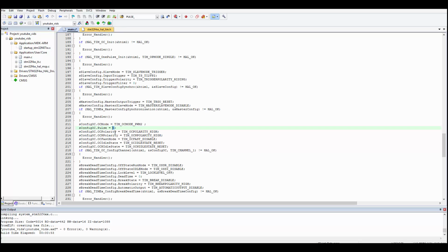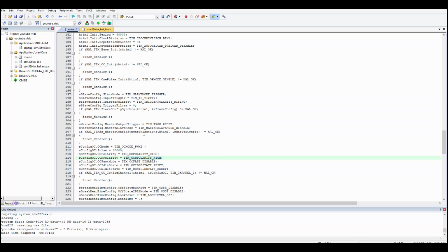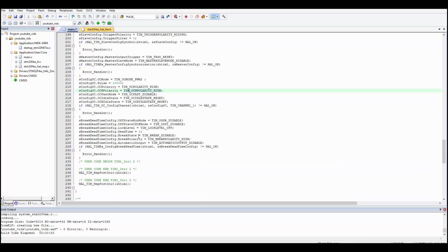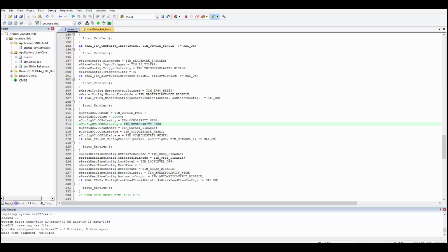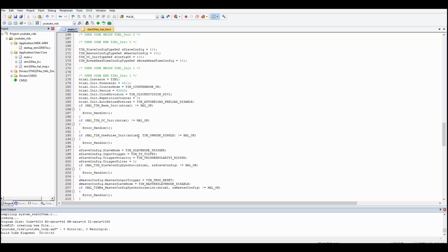For this application we are using 65 milliseconds, and if I write here about 10,000, it will delay for 10,000 milliseconds and signal will be high for 55 milliseconds. We will see this signal on the oscilloscope, and that's the configuration. I think it's enough for getting output.